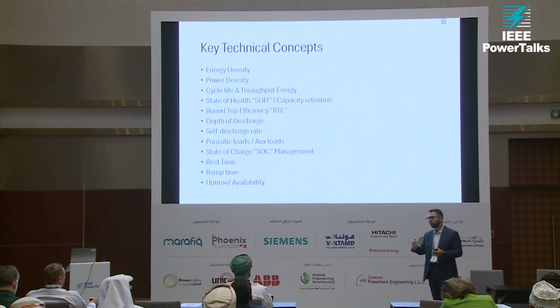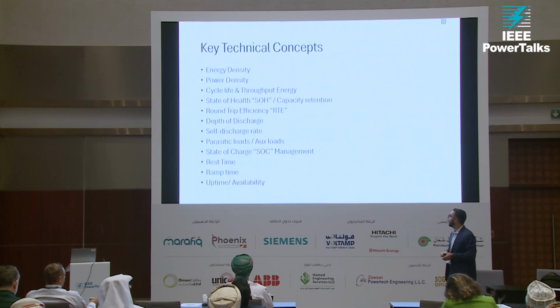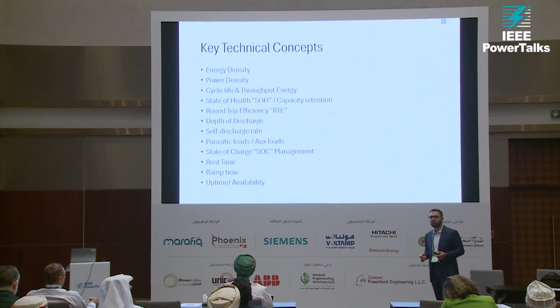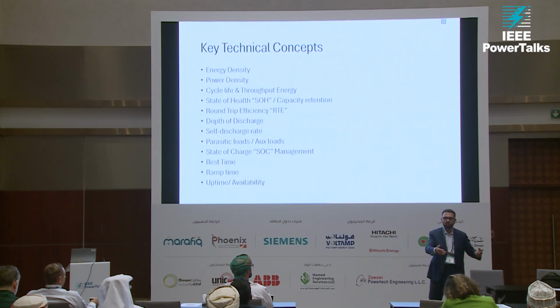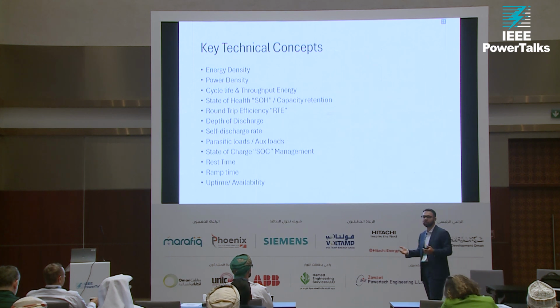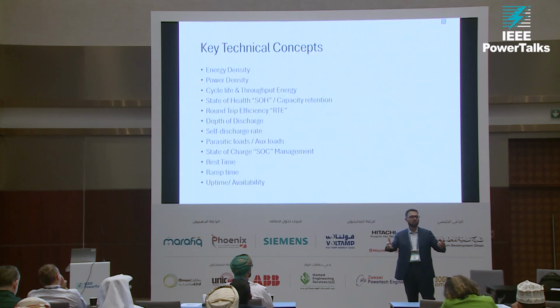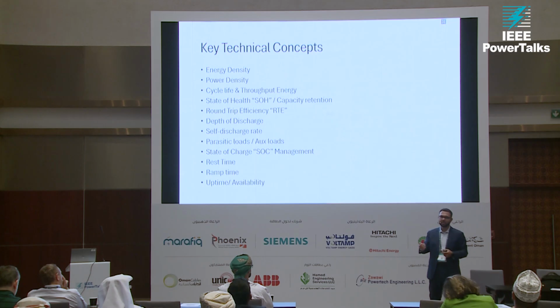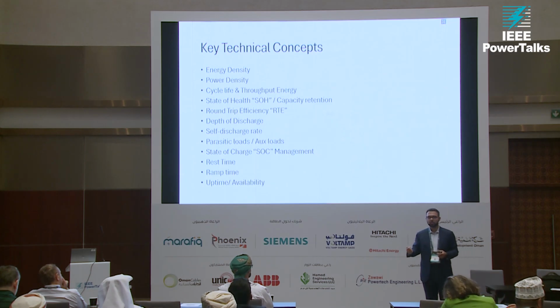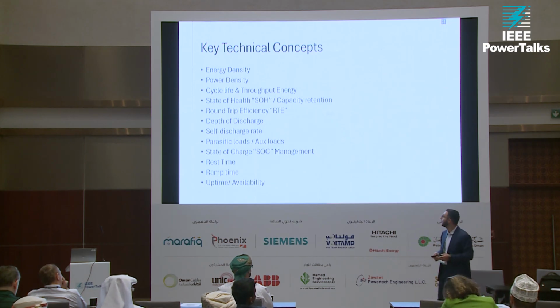The more you cycle, the more your battery is going to degrade. The less you cycle, the better your battery will perform. And different technologies have different cycle lives. For example, pumped hydro has an infinite cycle life. Other than the ongoing maintenance you have to do on your system, there's no reason to believe that your reservoir is going to be impacted. You have the reservoirs there, physically there. With electrochemical batteries, this is less forgiving. The more you cycle, the more stress you have on the battery.